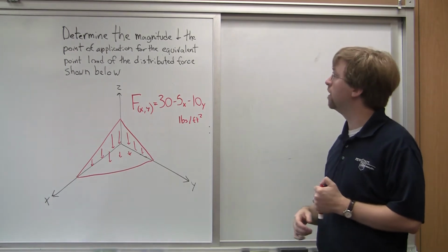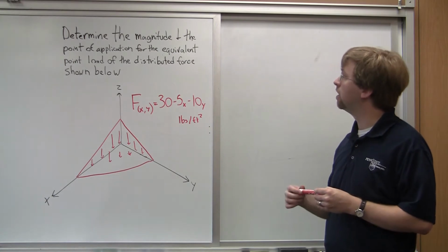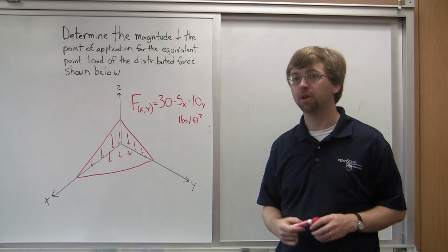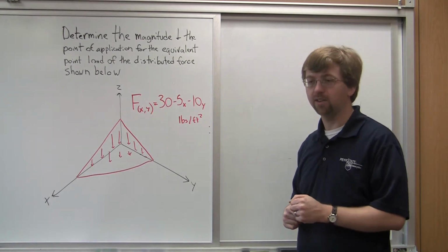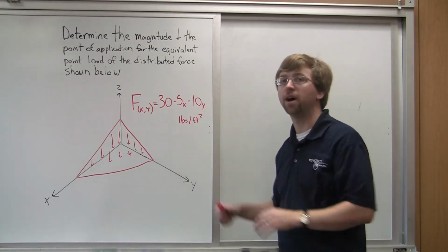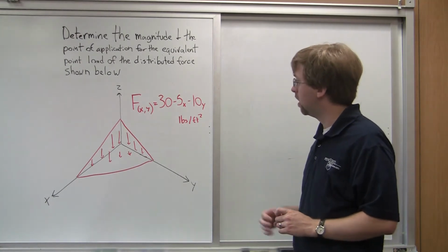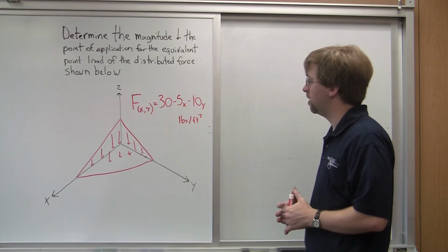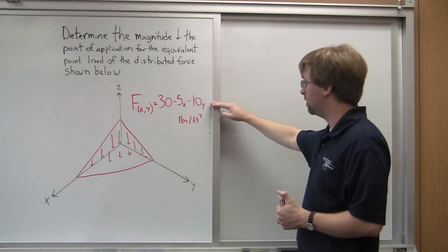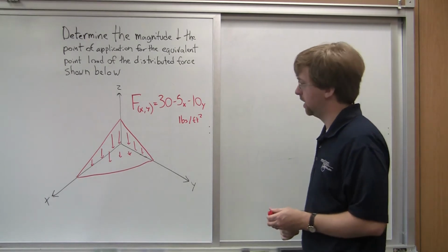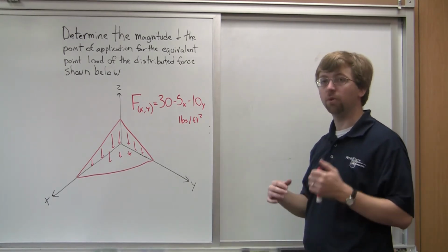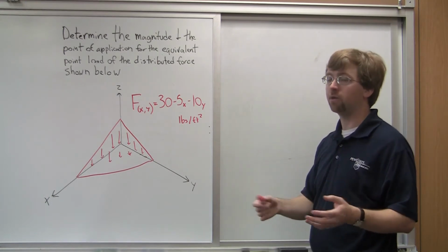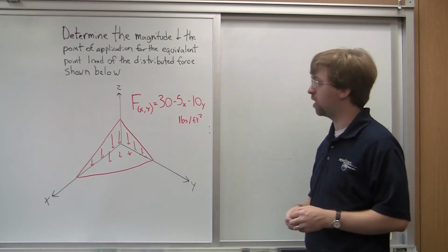And we're asked to determine the magnitude and point of application for the equivalent point load of the distributed force shown below. The original problem scenario online has an explanation of this as sand piled up into a corner like this. So this is our function, and we need to determine the force function that's given to us, but also the bounds of this. So since we've got x and y, we're going to need to integrate with respect to x and integrate with respect to y.